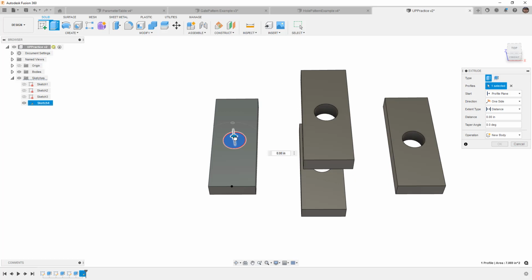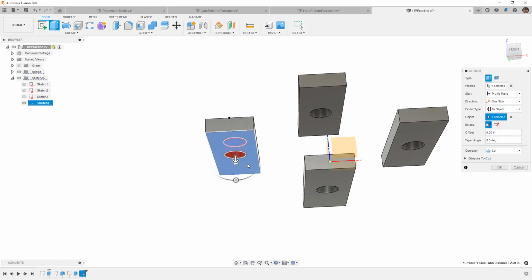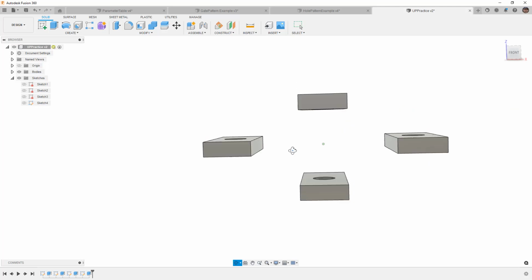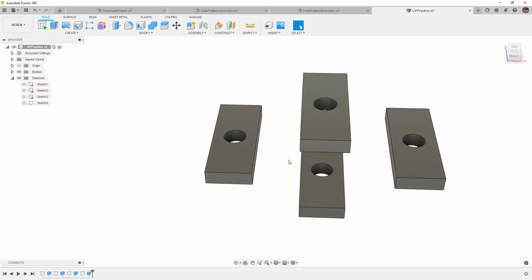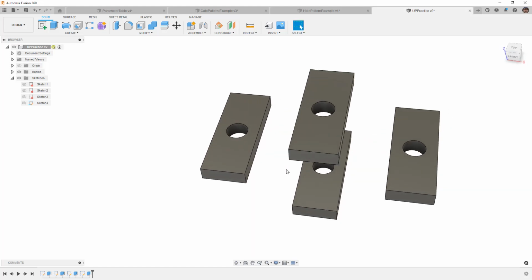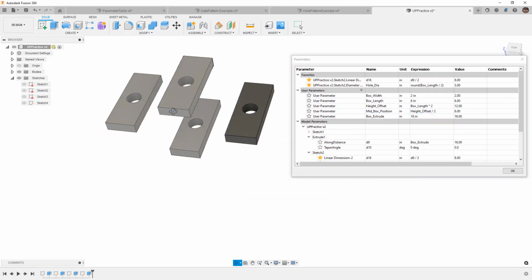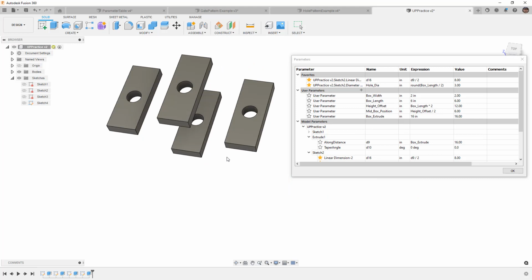This time I'm going to just pull it down. Again, I'm going to use toObject. toObject is a great option, especially if you're dealing with non-planar objects, or through all, depending on what your end result needs to be. So now we've taken a look at ways in which we can use driven dimensions, construction geometry, and a whole host of different options to essentially create the same thing.